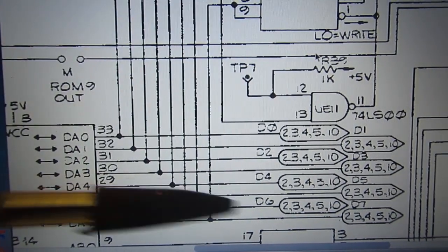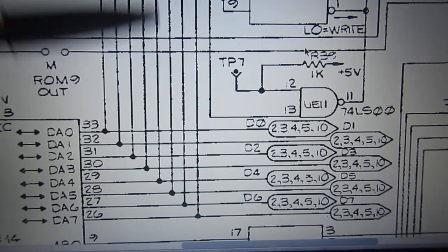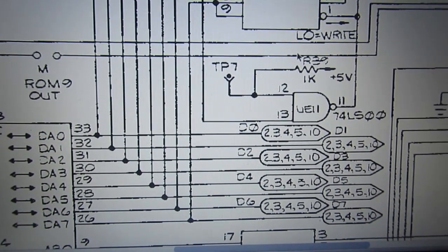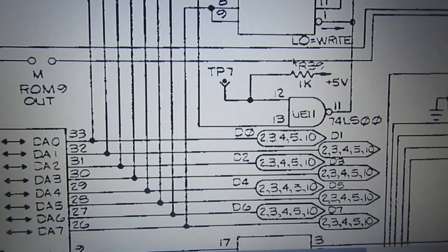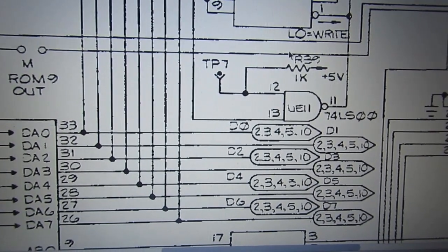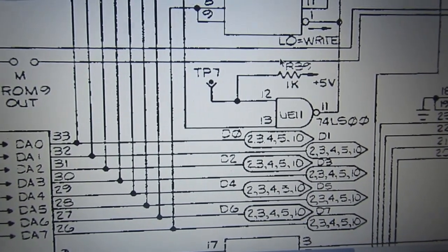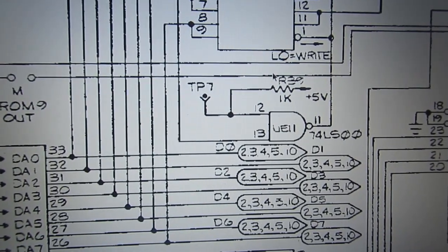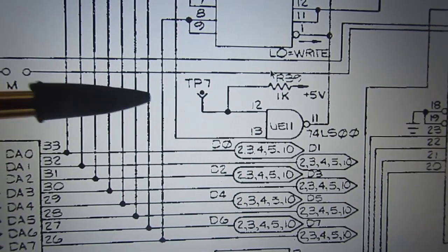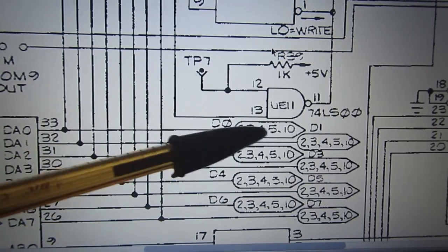Okay, let's recap everything. The test result A7 address bad was not very useful. The thing that was most useful is to let the test use the daughter board RAM, which was good, and notice the problem with the data 0 conflict due to the bad 4116.